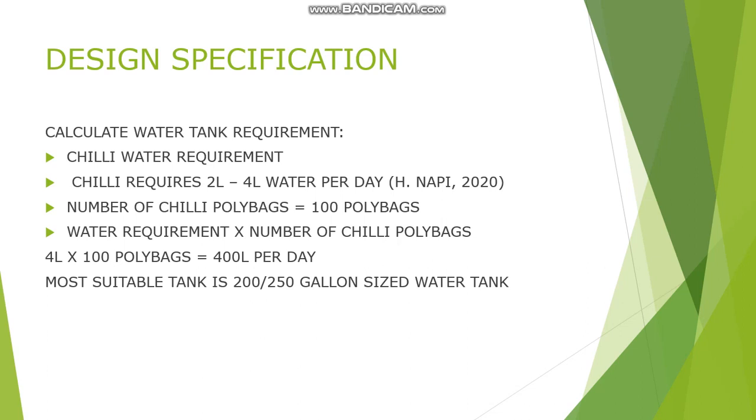Hence, the water requirement times the number of chili polybags equals 400 liters per day, the maximum needed water for a day. Hence, the most suitable tank is a 200 or 250 gallon water tank. 200 gallon is about 750 liters and 250 gallon is about 950 liters of water.